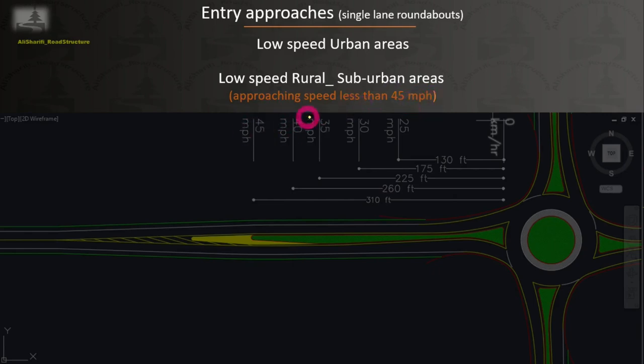But what approaching speed means here is where engineering judgment comes in, and some standards refer to posted speed or design speed as approaching speed. If there is a considerable difference between the 85th percentile speed and the posted speed, then you may want to consider the 85th percentile speed as the approaching speed.